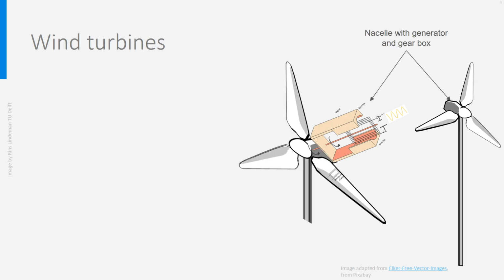After the energy from the Earth core and from water, it is time now to go to higher spheres and to look at how to produce electricity from wind energy. Here too again, AC electricity is produced in a generator, which is driven by a turbine. The generator is placed in the box behind the blades, the nacelle, together with a gearbox in order to increase the rotation velocity of the generator coil. The electricity produced goes through electrical wiring along the shaft to the grid.